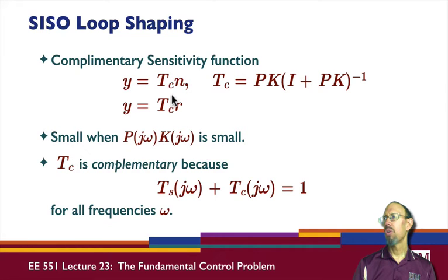In this case, that means my system is not sensitive to the noise, which is good. However, we don't want R to be acting in that same way at those same frequencies, because otherwise it will attenuate the reference signal and it won't work very well.